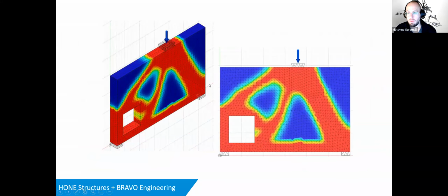So here they're experimenting with some of our other tools in Autodesk. In this case, it's Fusion 360. And they're using Fusion 360 to apply a load and then see where the predominant stress lines will show up in that wall of potential concrete. Once they had that shape, then they brought that shape into Dynamo as an input, as a Revit geometry piece.